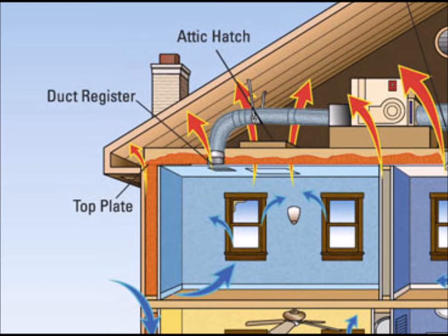First, we look at the interior air barrier methods. We have the airtight drywall approach and the airtight polyethylene approach. The exterior air barrier methods are the airtight sheathing approach and the airtight wrap approach.